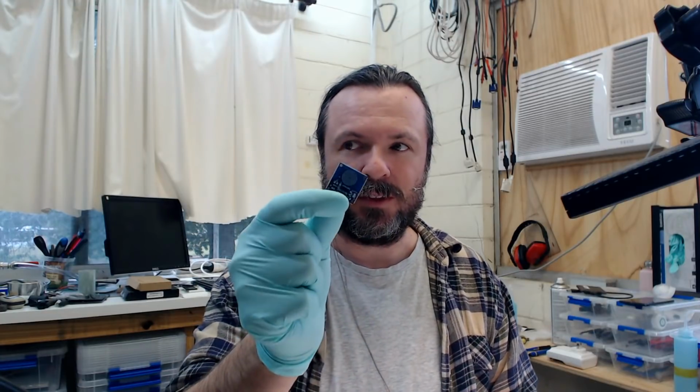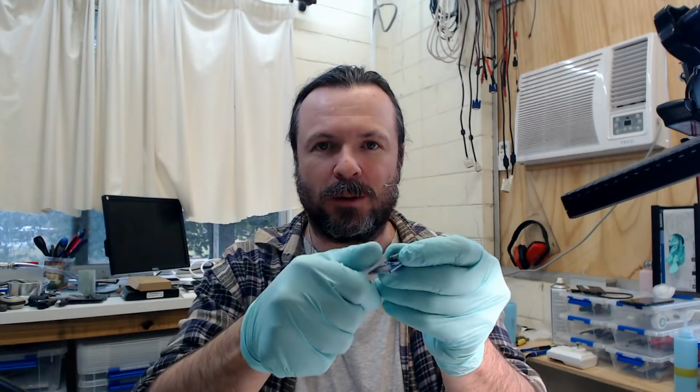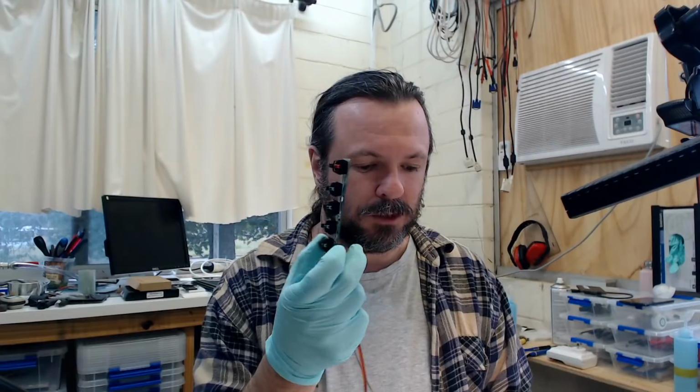But it's an inconvenience at times, because a device like this in particular has an active drive on the signal line. It will actually push 5 volts out on the line when your finger comes near it, and that conflicts with the fact that we've got an internal pull-up. So what I have to do is rewrite the software for this to handle the fact that this is an active drive.